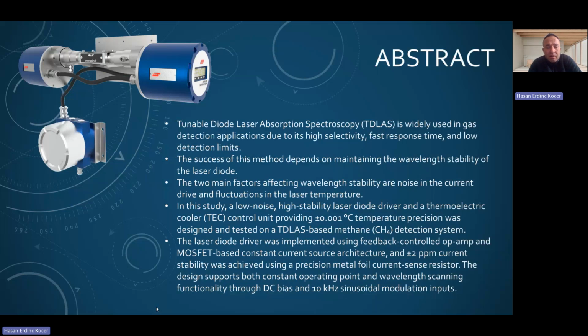In this study, we present a low noise, high stability laser diode driver and thermoelectric cooler (TEC) control unit providing 0.001 degree Celsius temperature precision. It was designed and tested on a TDLAS based methane detection system.